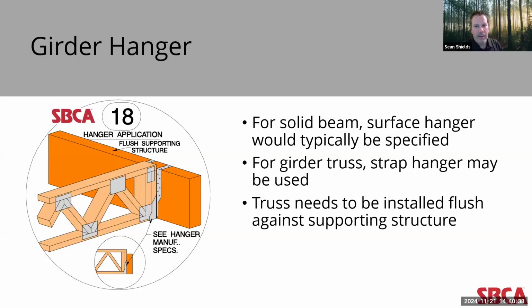All that being said, the point of this detail is that when using hangers, no matter what their type, the truss needs to be installed flush against the supporting structure, whether it's a beam or an exterior wall or a girder truss.